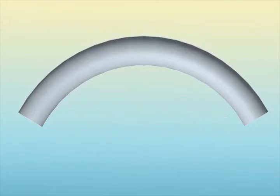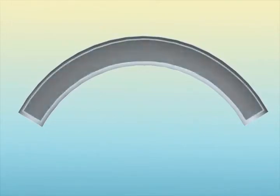First, air comes from the line itself. A pipeline isn't really empty prior to startup, it's full of air. To entirely fill the pipeline with fluid, you need to eliminate that air. As the line fills with water, much of the air will be pushed downstream for release through faucets and other outlets, which still leaves a large amount that will become trapped at system high points. This occurs because air is lighter than water and will collect at the high points. This pocket of air will continue to grow as it's fed from other sources of air in the line.